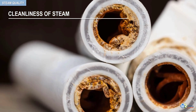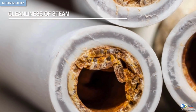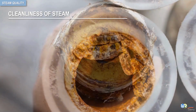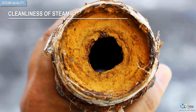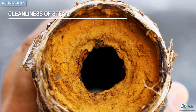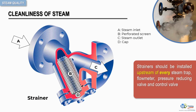These fragments will have the effect of increasing the rate of erosion in pipe bends and the small orifices of steam traps and control valves. For this reason, it is good engineering practice to fit a pipeline strainer. A typical example of this is now shown on screen. This should be installed upstream of every steam trap, flow meter, pressure reducing valve, and control valve.